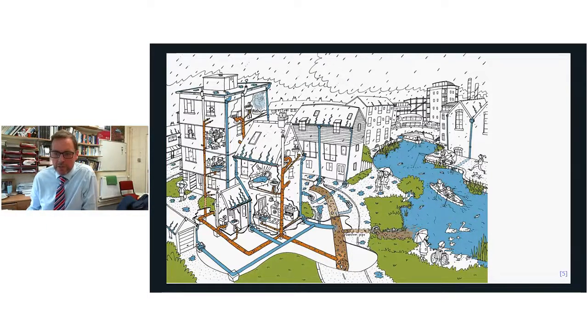And they all come together into the foul pipe, and then they connect together into this pipe which is running through the centre of the picture, along with the surface water flows during rainfall events. Now, partway down that we've got the overflow pipe, which is basically our CSO.